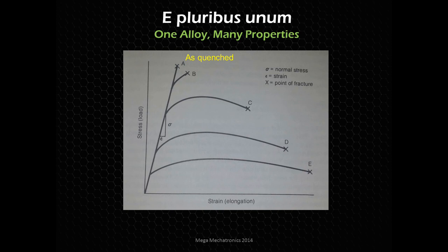And you don't want to leave it, especially in a manufacturing environment when you're moving parts around. You don't want any cracks to form, people banging stuff around on the high-low truck. You need to temper it, any temper. So let's say we do a low temper where it's at a lower temperature or shorter time or a combination of both. Here's maybe a higher temper where you are bringing it up to a higher temperature and you're leaving it there for longer. And here's possibly a normalized material, and then a full anneal where you're resetting it.